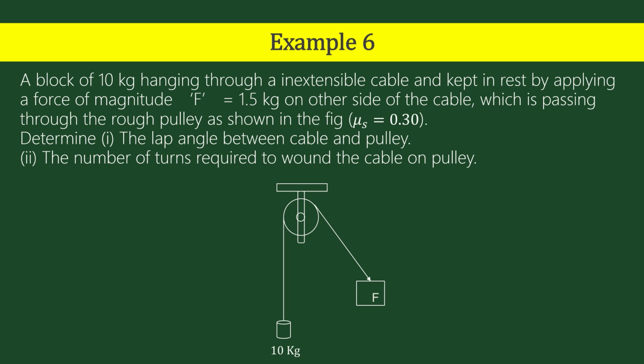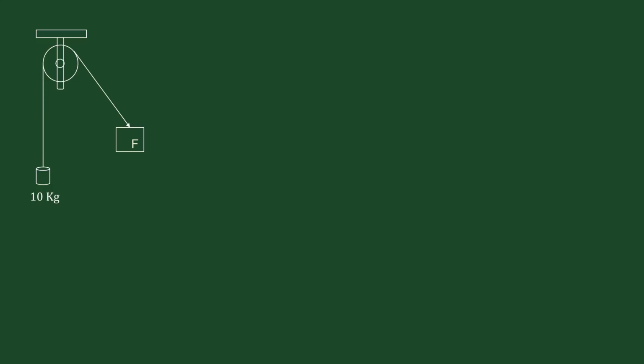See this diagram. In this case we need not find the lap angle from the diagram, but it is very clear from this figure that it should be greater than 90 degrees. Once again, 10 kg is given, and as we are going to take the ratio of the two forces T2 and T1, there is no need to convert kg into Newton.